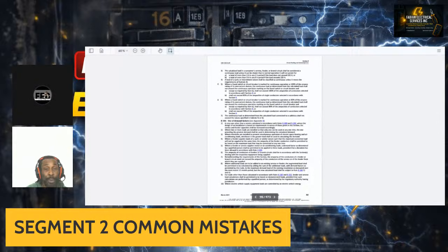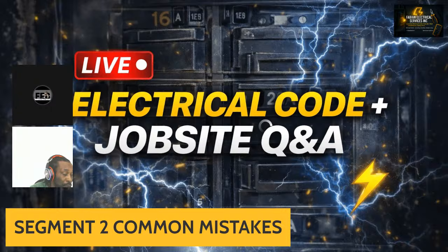circuit that you need. Again, guessing circuits. A lot of us guess circuits instead of seeing what it's drawing. That's how you size your wire and your circuit: going to the code book and looking for the actual rule that's there. It is inside of the code book. You will find it there. When you're sizing your circuit, always make sure to size it from the code book.